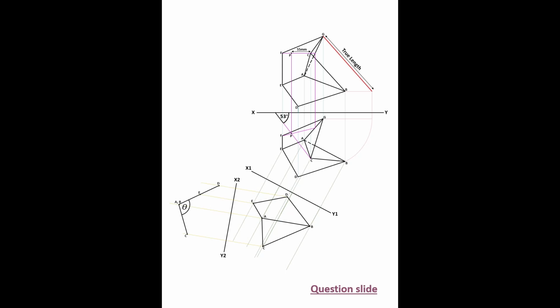Auxiliaries and true lengths and true shapes, they go hand in hand. So there was another true length using a different method here. That was our rebatment method, using the compass, bringing the lines across, getting it horizontal in the plan, and true length in the elevation. So locating missing points using sliding set squares, that was also part of the question. So obviously AE and GF, we had to use sliding set squares to find F, both in plan and elevation, and finding traces. So obviously 55 from point C, we got our points.